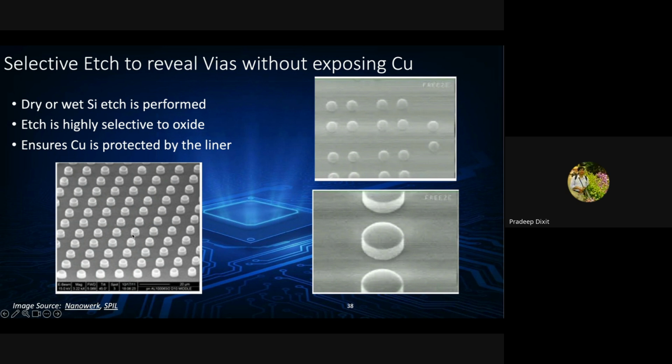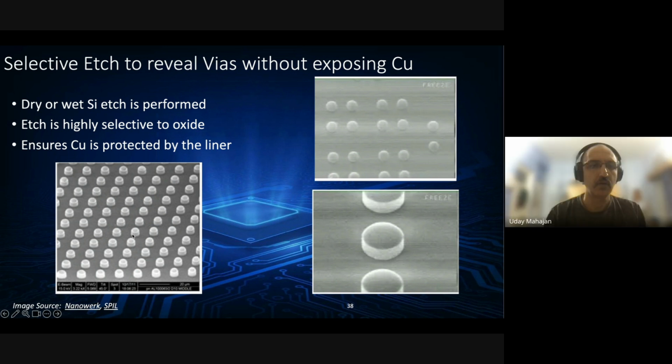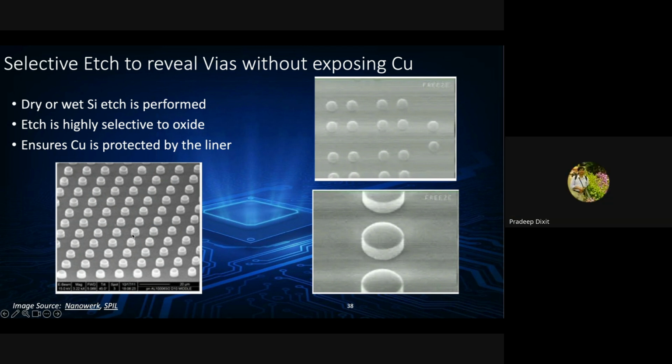Well, how old is your data about this 5 to 7 micron variation? Is that the latest? Let's imagine we have a starting wafer thickness of, let's say, 700 micrometer, correct? Even if we consider, for example, 1% variation from the edge to center, which is a normal one, because in a 300 millimeter wafer platform, controlling the plasma distribution is going to be a very difficult task, right? So I'm assuming 1% variation.